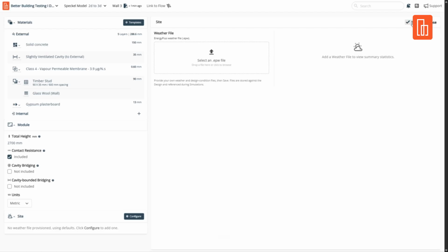The useful bit about doing this is that you can then interrogate your climate file, make sure that it has the data that you expect it to have for a hygrothermal study. I'm talking particularly about precipitation data here. If it has no rain within the data file, it's pretty useless from a hygrothermal point of view. So it's well worth doing that, because even data assumed to come from reputable sources, we still see data points missing or data points much lower than what you would expect. It's important for you to contextualize as you do these studies.